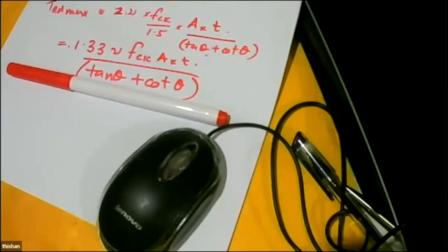Now, you worry about torsion only at one place. Either you have a cantilever projecting out from a beam and exerting the moment, or else a big beam like a transfer beam where the loads are not on the center. That's the only situation. But be aware that you have to be concerned.